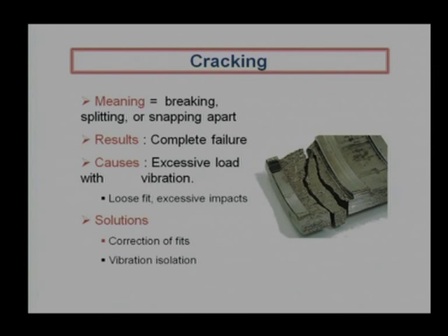So, the end of the fatigue comes with the cracking. Many times we apply a very high load on the surface, not intentionally, but because of some malfunction, some sort of overload or misalignment, or some problem in assembling the components. In that case, a very high load will generate a crack through and through from the top to the bottom surface, and that is known as the extreme case of failure. That may happen spontaneously also, within a few hundred cycles.